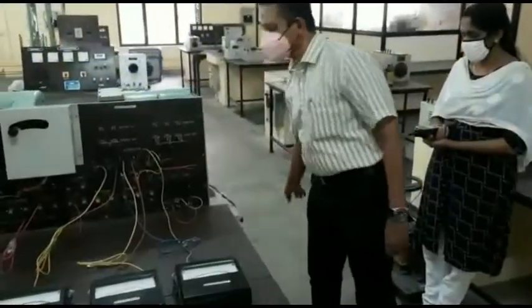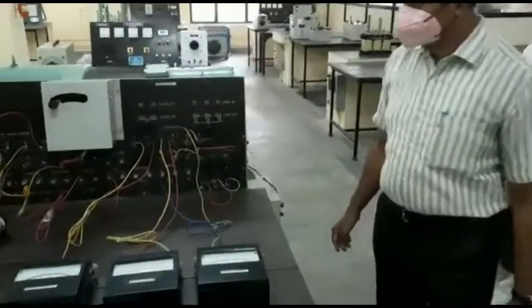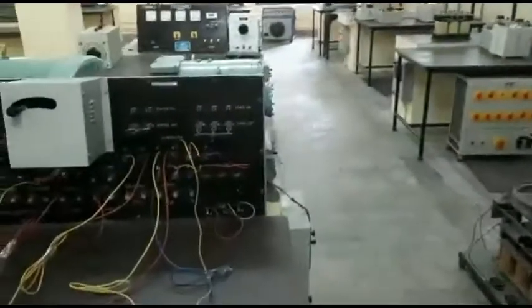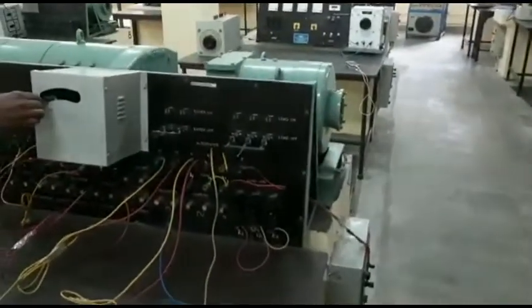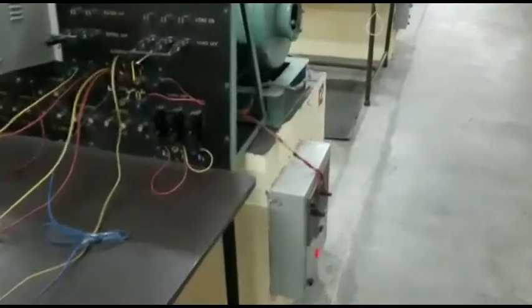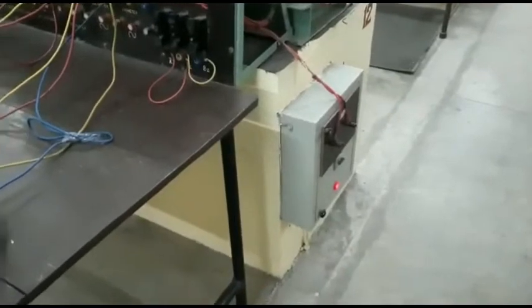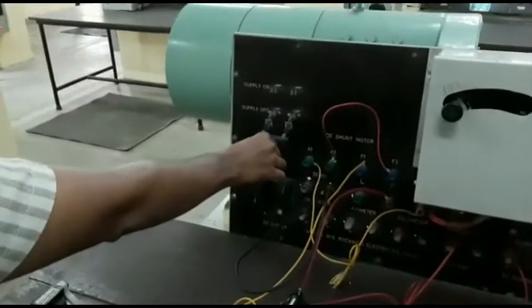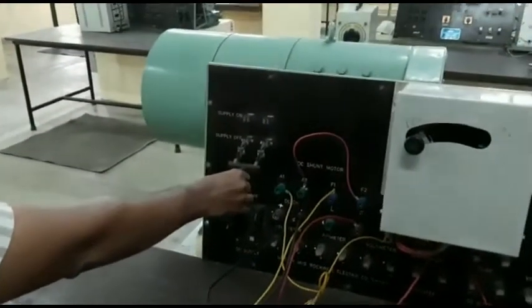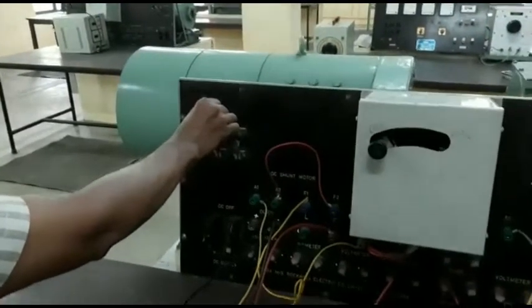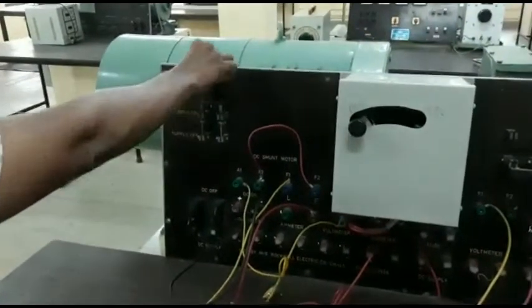Today we will be performing the experiment now. We have already traced the circuit. Initially we will discuss the DC supply. The sir has switched on the DC supply now. The switch is in on position. So now the DC supply is available at the DC supply point, positive and negative. With the help of this knife switch, the supply will be available at the L point of the 3-point starter. So sir is switching it on.